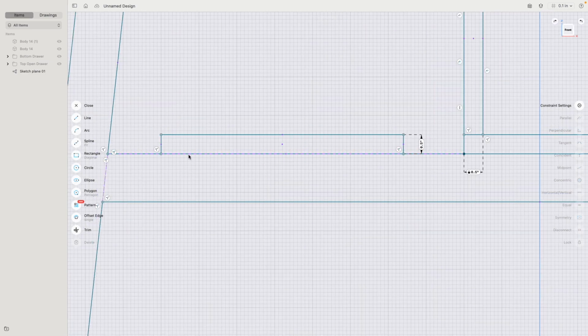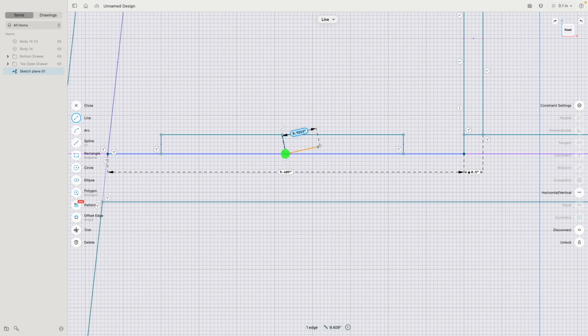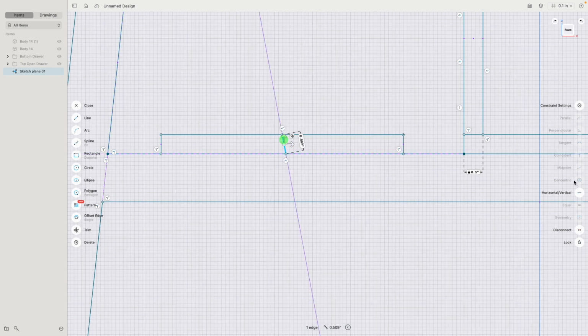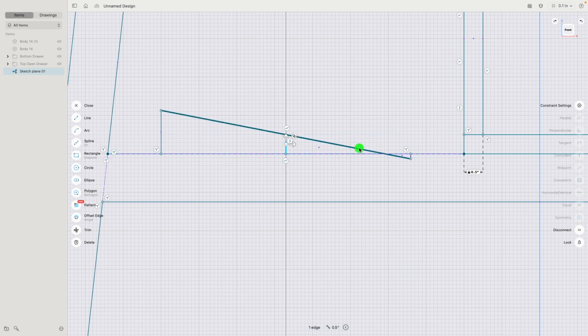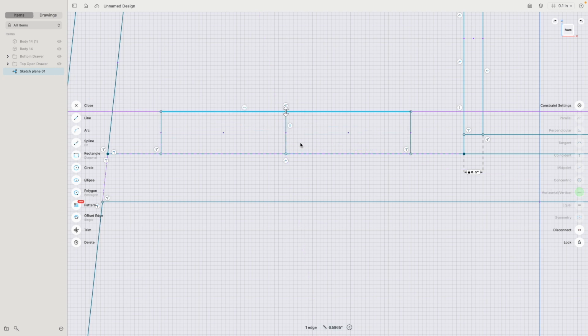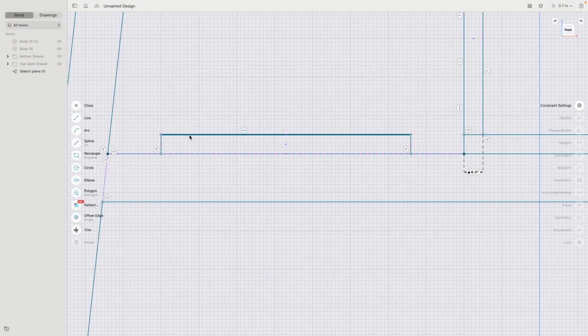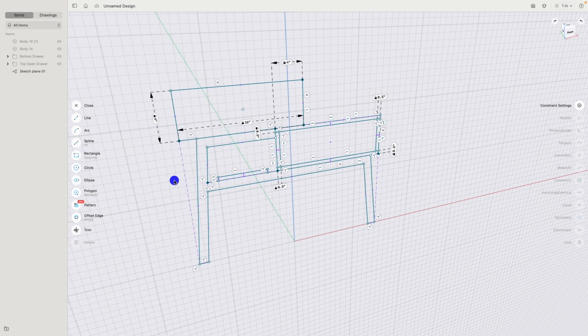Here's a little trick. I will lock these two parts. You see we have midpoints there. From there to there, select, escape. This line I make horizontal. This line I make horizontal. Vertical. And then this dimension we set to 0.5. That pulls it down. And then this line I remove. So I actually use these midpoints to center everything. Very good.